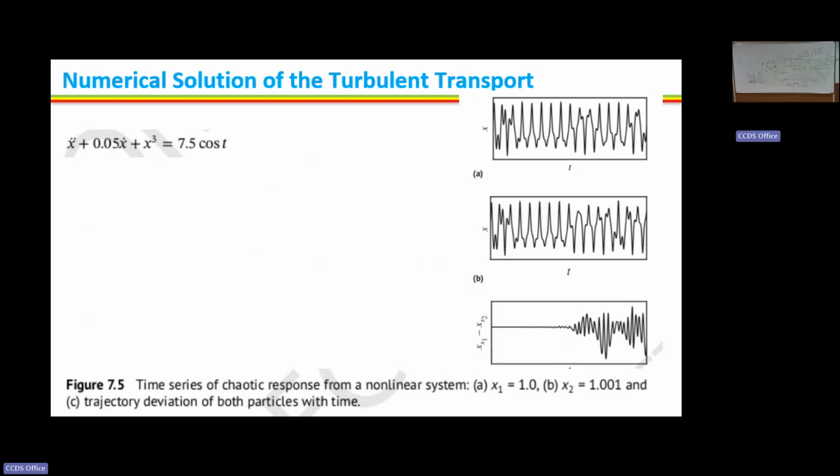And this perturbation may be introduced due to a large grid, or due to an improper numerical scheme. If the numerical scheme is not sufficiently accurate, there may be some error during numerical truncation, right? Those small errors may give you a false result instead of the true result, right? So you need to be judicious, you need to be a little bit experienced, and you need to spend time to know what exactly you are doing, whether your grid is sufficiently resolved, your numerical schemes are sufficiently fine, and you are doing everything correctly.